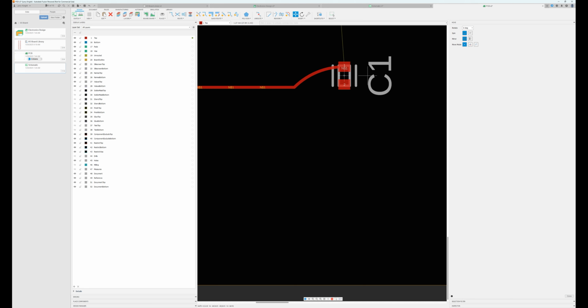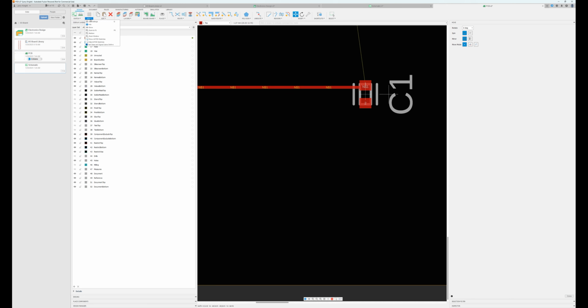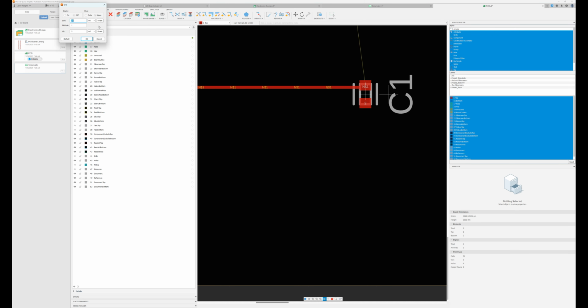And you can change the grid too. You can hold down Alt so that it's a finer movement, finer alignment. But you can also come up here, where we went to grid settings before, and we're back to mils because this is the PCB, I guess. I don't know why it changed. Maybe I closed it earlier when I was messing around. But anyway, millimeters.